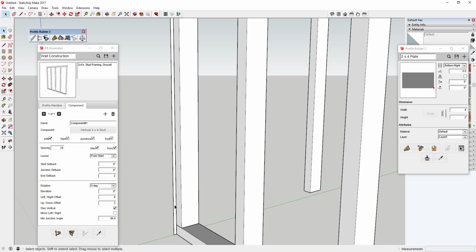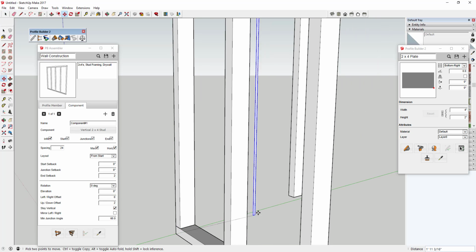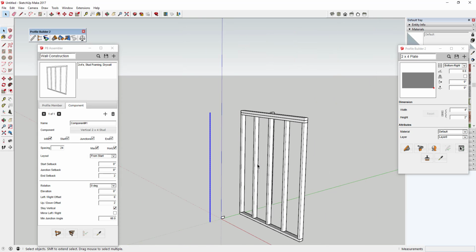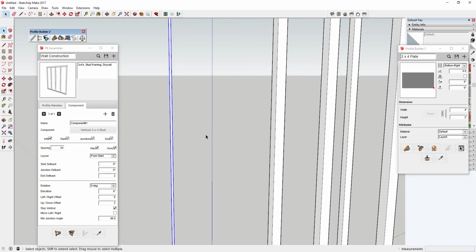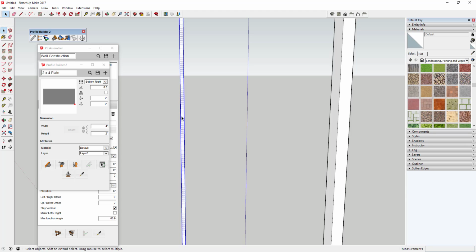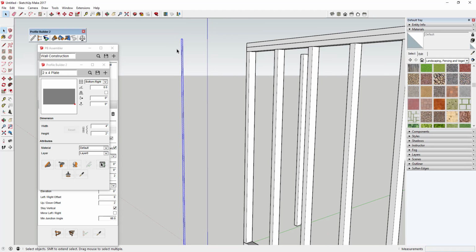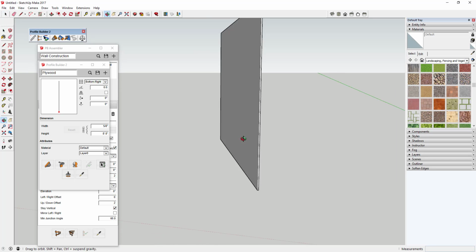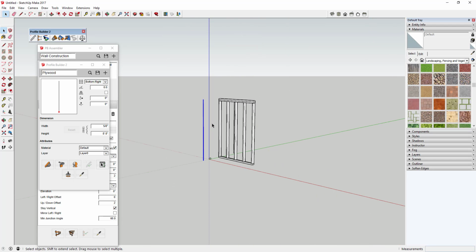Then we'll close it just like this. We'll go ahead and move it out of the way for now. I was just using that wall as a guide point right there. And so what we're going to do is add a profile for this. All that means is you're going to double click to select this little 3/4 or 5/8 inch object that you drew, and then just click add. We're going to call this plywood and hit OK. Again, we're going to set this to the bottom right. Now if you draw this, you can see it's going to create a 5/8 inch sheet object right here.